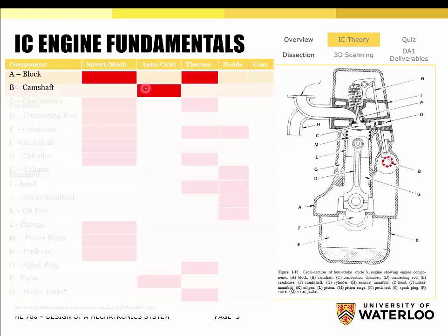However, you need to be able to support the loads. It's a steel component and there's things pushing against it, like the valve actuators, which are called the push rods. You can see this long rod here is pushing against it. So there's going to be things like frictional forces, wear, bending, torsional vibration, all these things that play into structural and mechanical as well.